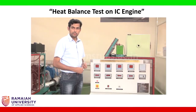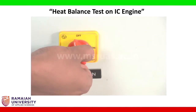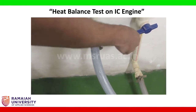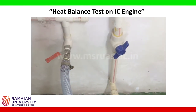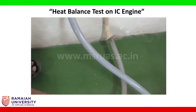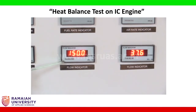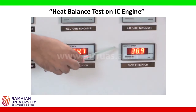To conduct the experiments you have to follow the procedure this way. First, switch on the display unit. Supply to the eddy current dynamometer has to be switched on here. Then water supply to the engine has to be supplied here. Both the water is flowing in the channels here. Now the flow rate to the engine has to be set to around 160 cc per second, and to the calorimeter around 40 cc per second.